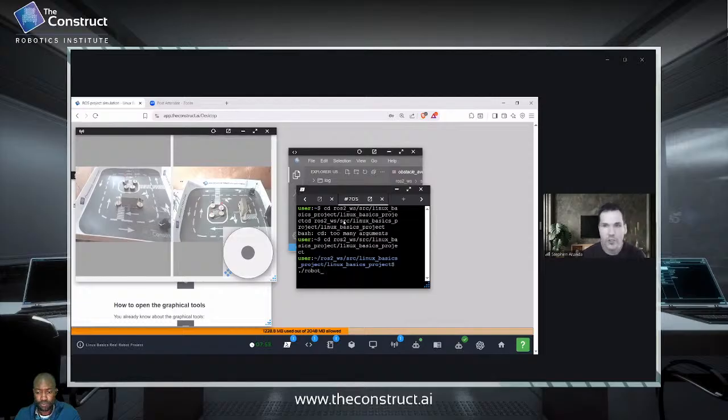It turns, waits for a delay, then stops and reevaluates by getting the frontal laser readings again. If there's no obstruction, it moves forward. It basically does this in an infinite loop until I kill the application.